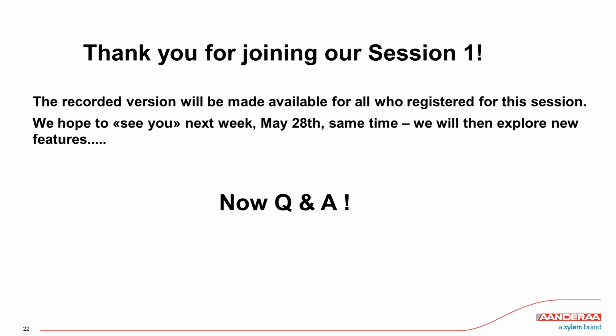We so far have not seen the purpose of having a push button on the display, because you either want to stick to pounds and feet. If the rig moves to waters which use metric units, they will show metric units, but it's not like you want to see pounds in the morning and tons in the afternoon. So you can still do that, but you have to open the computer cabinet and then use a switch or an external key switch, but not pressing a push button on the display.